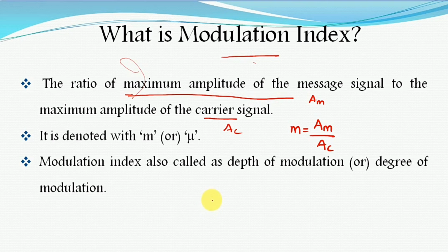While transmitting through the wireless channel, we use a modulation technique. We convert the low frequency signal to a high frequency signal with no information change, and thereafter we transmit through the channel. At the receiver end we have to use a demodulation circuit in order to recover our original baseband signal that was transmitted at the transmitter end. How much percentage of recovery there will be is indicated by the parameter modulation index.